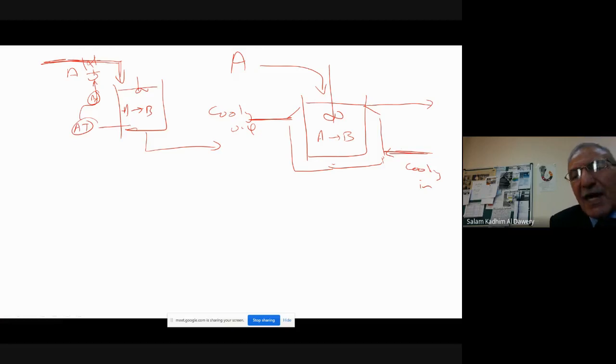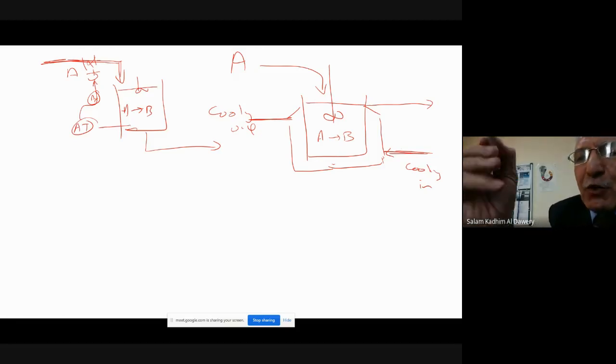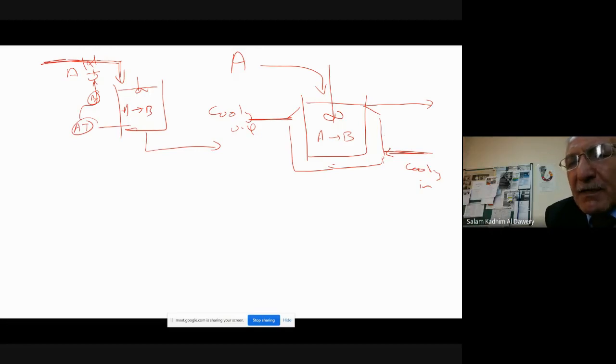So what do you do for control here? As you understand, there is a big relationship with the temperature based on the Arrhenius equation. So you may control the temperature, right? So you use a temperature transmitter, temperature control, and we may use the cooling media out to control the reaction. You control the temperature rather than the concentration. Or you may have both together. We call it cascade control. Or even you can have both. Never mind, it does not make any difference.